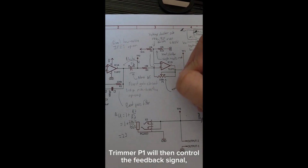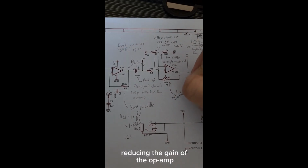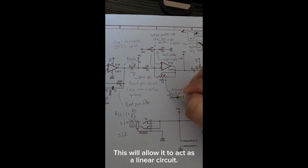Trimmer P1 will then control the feedback signal, reducing the gain of the amplifier, which will not saturate the output voltage, and this will allow it to act as a linear circuit.